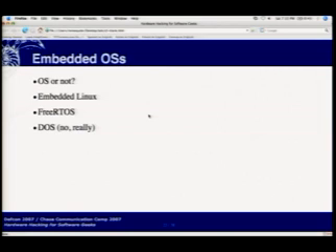Now, the next thing you'll need in making your own embedded device is to decide which way to go, whether or not you want an operating system at all. Some things that can determine this is if you have real-time deadlines that you have to meet. Let's say you're doing some sort of control application for an airplane, and if you don't send a certain signal every 500 milliseconds, the engines stop. Basically, that's a hard deadline. You need a real-time OS that will schedule things based on deadline priorities to make sure that all those deadlines are met.